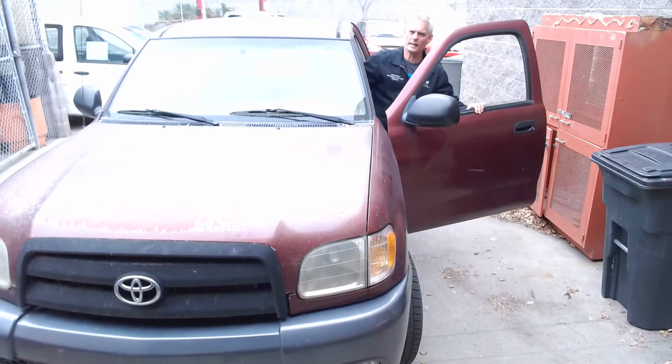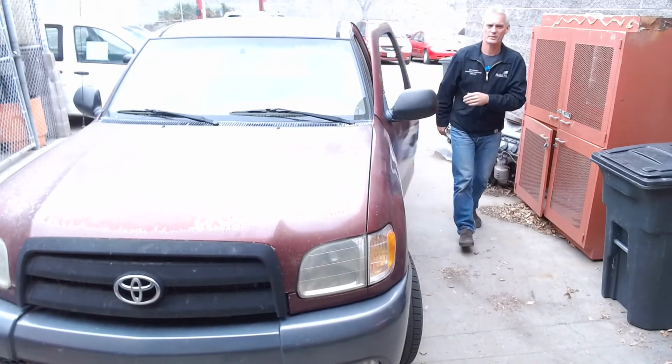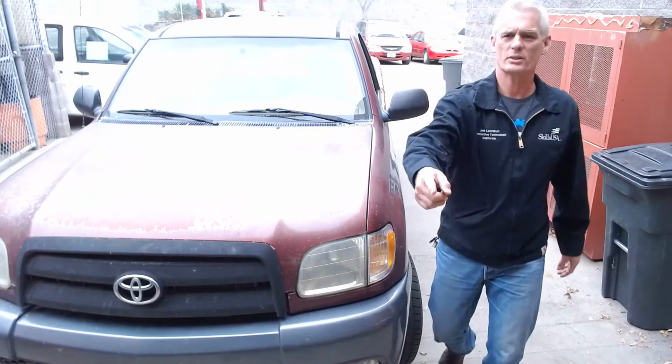Okay, so you should have been able to see pretty clearly, because I could see the headlights bouncing off the computer, and I could see that the light was dimming while it was cranking. So that's normal. The cranking speed is normal. The car starts within a few seconds. The headlights do dim. That tells me the starter is pulling power. The voltage, the electrical pressure of the battery, is dropping down because it has heavy load and it's trying to push current through the starting system.